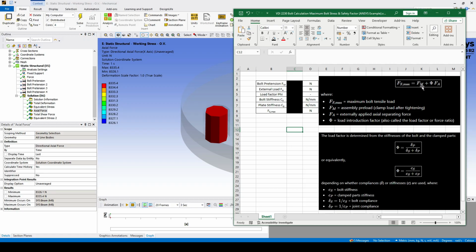and this is already known to us. As I mentioned before, for our bolts we are using 18.6 kilonewton. In case you have in your model or other application another bolt size or strength class, you can check my previous videos. I also already mentioned a table that shows the bolt pretension for all bolt kinds, sizes and strength classes, so you can check it.